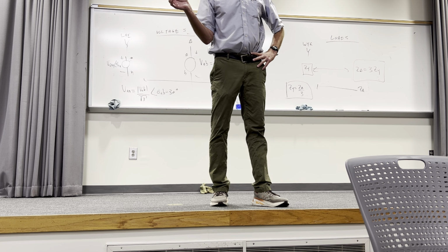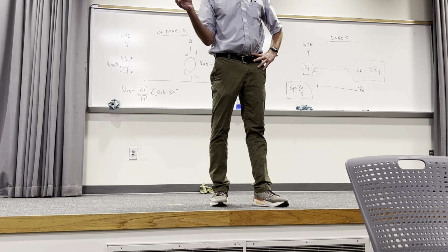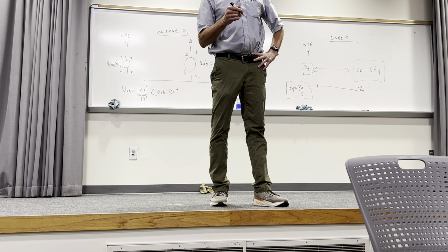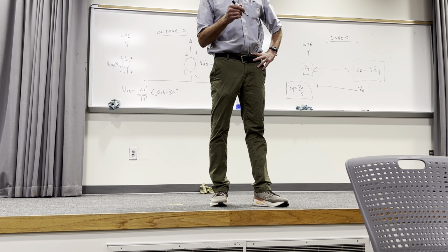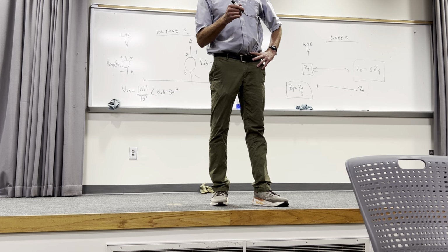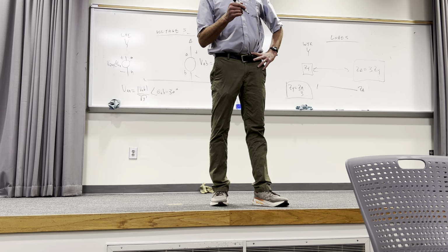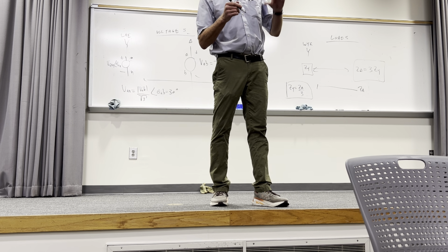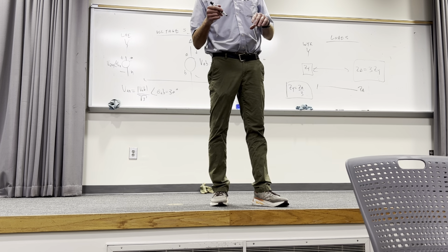Now, anytime, and the last time I said, anytime you're doing the problem class of 3-phase circuitry that we're talking about, you always take the delta configuration and turn it into a Y. Then you get the line currents. You all hear me on that? Anything else that's asked for, either the Y voltage or delta voltage or delta anything, you get from the Y information. I'm trying to be absolutely clear about that.